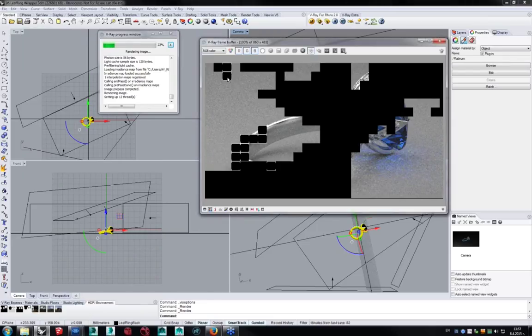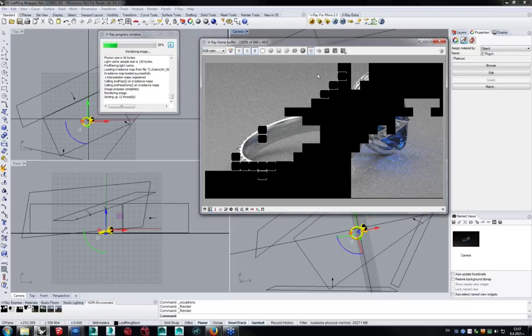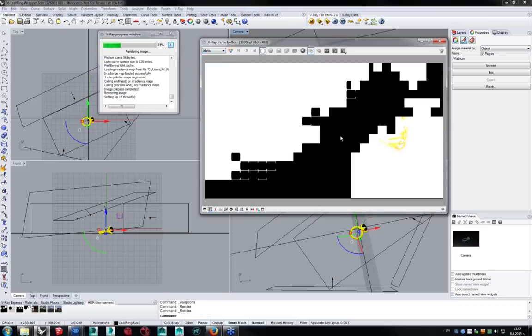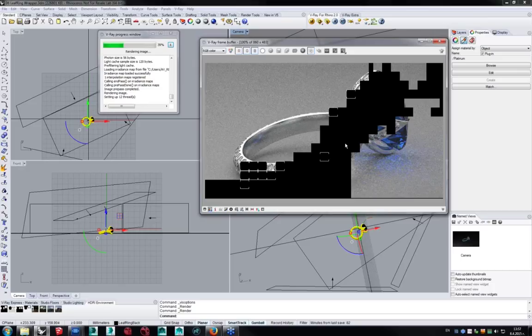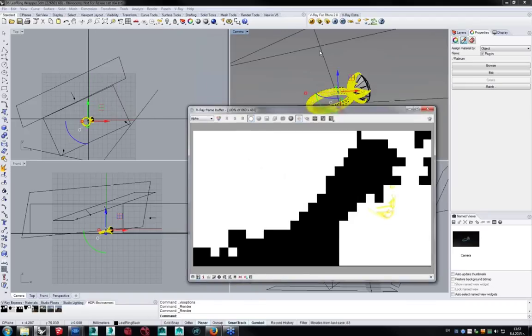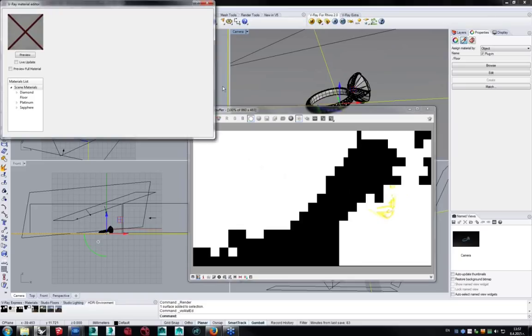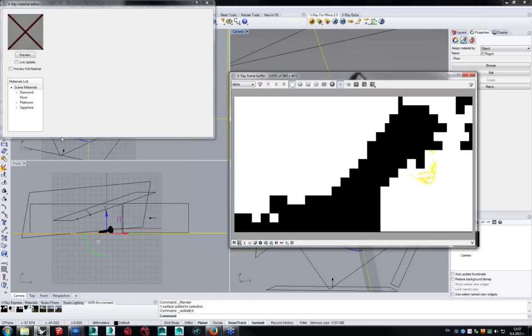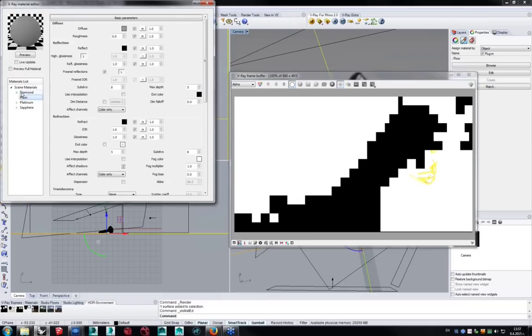There we go. Now one thing that many people want to do is have the ability to change the floor or the background once the rendering has been completed. So they use the alpha. Now currently our alpha is not good because we haven't detached the floor from the rendering process, and this is something that is not very good. So what we can do is use the V-Ray options, V-Ray properties, or the wrapper material. So let's go to the materials, and we have floor.